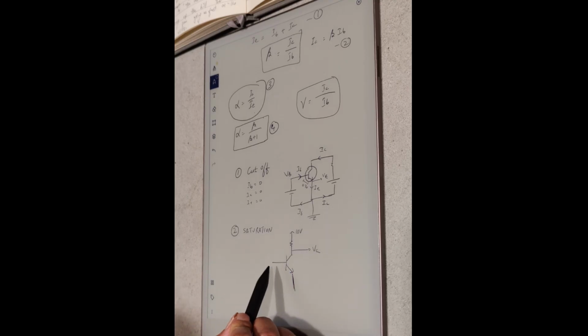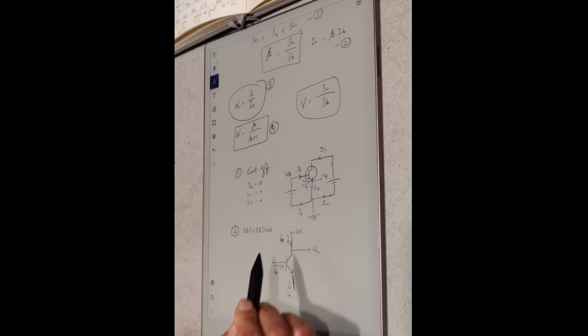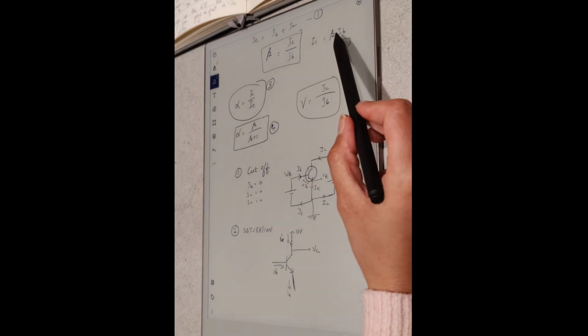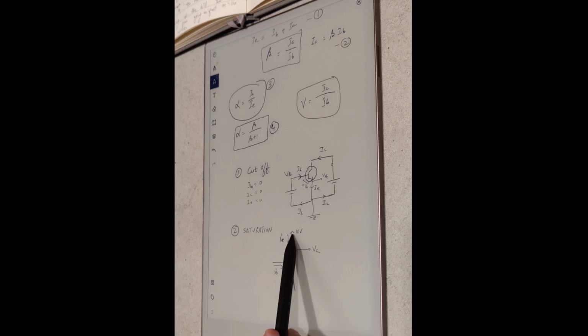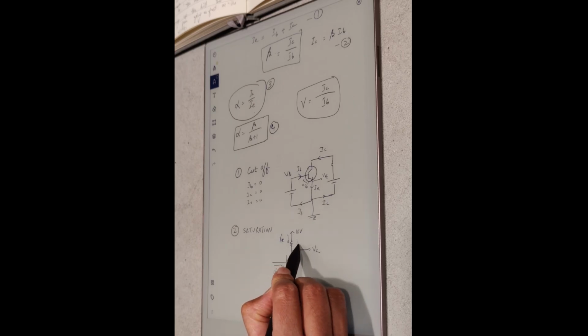We know that the base current flows like that, IB and IE. So this is IB, this is IE, and then the collector current also flows downwards into the collector, so this is IC. Now if I increase this IB, then I know that IC is going to increase. When IC increases, there's going to be a current that flows through this resistor, and there's going to be a potential drop, and the potential drop that is going to happen here is IC times R.